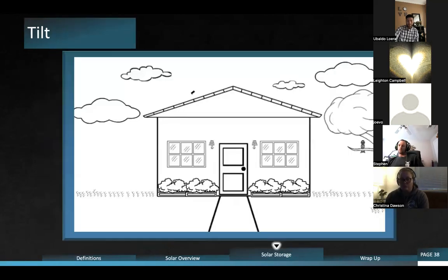What does the customer want to know when they're getting solar panels on the roof? Is it going to look like this? This is what a tilt looks like. We've all probably seen a system or two in our neighborhoods that have a tilt like this. It's not a bad thing. It's actually a pretty good thing for the customer. But for an extra panel or two to be a little bit more aesthetically pleasing, we do something a little bit different. We make sure that we get the right azimuth, we get the right tilt, and we get it flush mounted directly to the roof. If the customer is more about function than aesthetics, absolutely, we could drop a couple of those panels and tilt it on the actual roof itself.